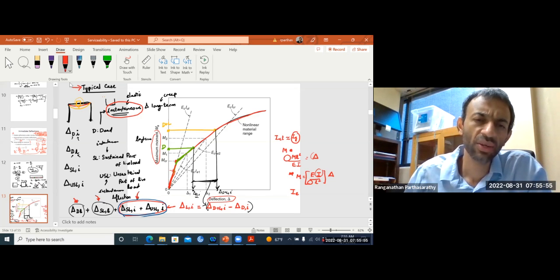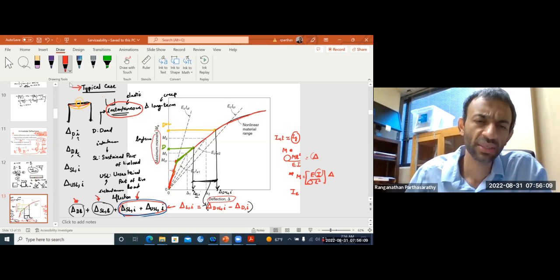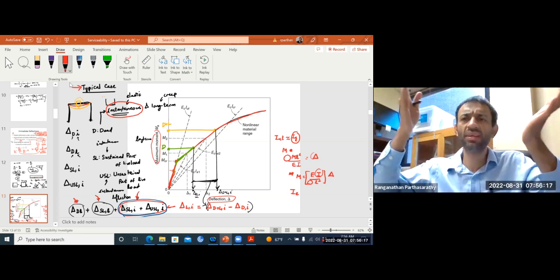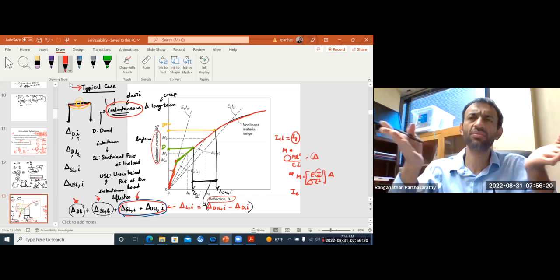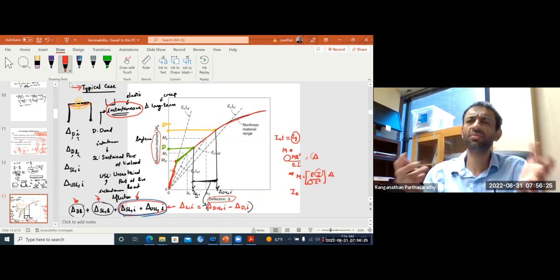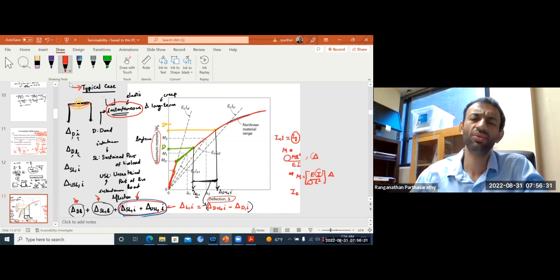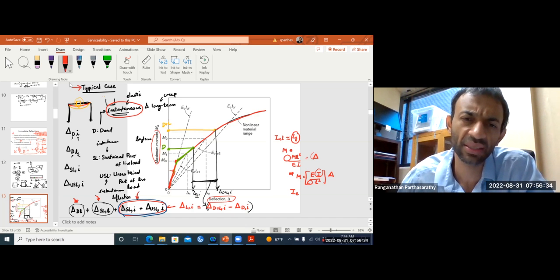So now, that is almost always not the case. Let's say that the green one that you see here, that is the dead load, and the yellow point is dead plus live. So you cannot just calculate deflection for live load separately. It will not give us the right answer. Okay, what we need is, after the dead load is already acting and you have the elastic deformation due to dead load, now when you bring in live load and it has further deflection, what's the difference? What's the additional deflection due to the live load? That's what we are looking for in the most typical scenario.